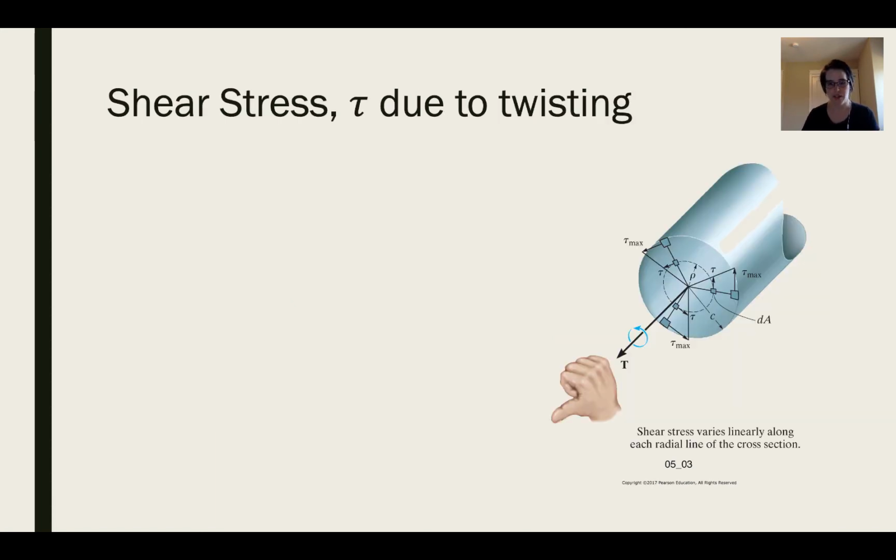So now that we've defined the polar moment of inertia, J, first there, we're going to go back to that formula that we had. And note that the maximum shear stress, rearranging it just a little bit, is equal to the torque times the radius of the pipe divided by the moment of inertia. And that will work regardless of what cross-section you have, because J is something that changes based on cross-section, and you can go and calculate the right J for your cross-section. So that's the maximum shear stress.